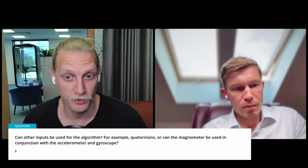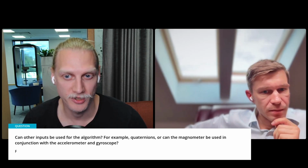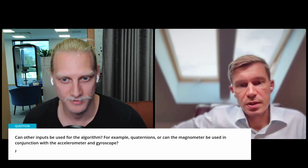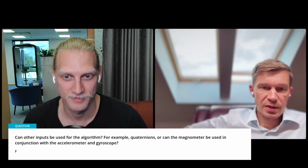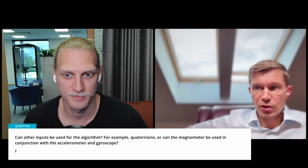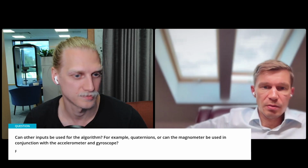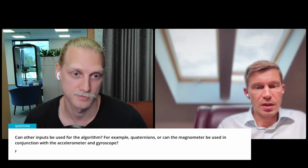Then there's a question if other inputs can be used for the algorithm, for example, quaternions or the magnetometer to be used in conjunction with the accelerometer and gyroscope. Sure, of course. As long as the data sampling frequency, if it comes from the same sensor, for example, accelerometer, gyroscope, and magnetometer, is synchronized according to the timestamp, then yeah, sure. If it comes from different sensors and it has a slight deviation in timestamps, then you could do some pre-processing to interpolate the blank spots in between them and just have them represent the same window. But yeah, sure, any data is applicable.